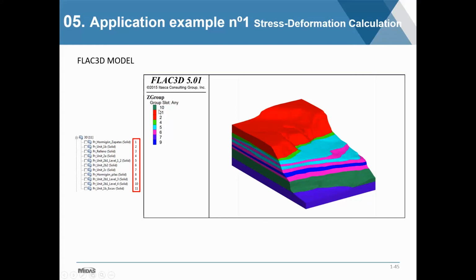We notice that there's no information for the footing, which would be zone property 1, as well as for the pier, which would be number 8. So we see that those zones are not activated here yet. We've now gone through the first stage of excavation, so we now have deactivated zone 11, related to the first excavation in the other Midas model. And now we get to the stages where the footing has been activated, what would be zone 1, and then eventually the pier as well, which is zone 8.